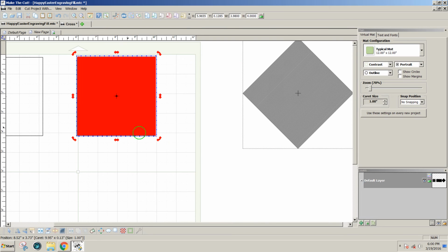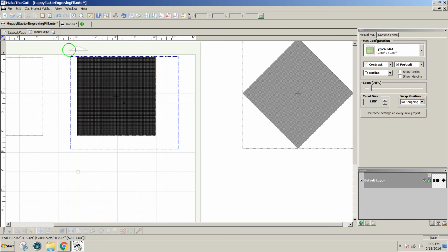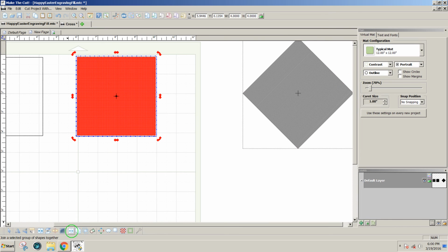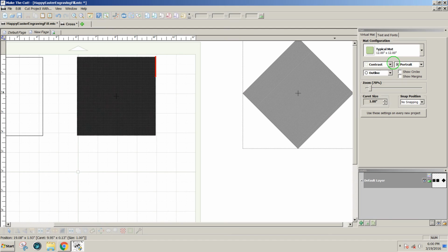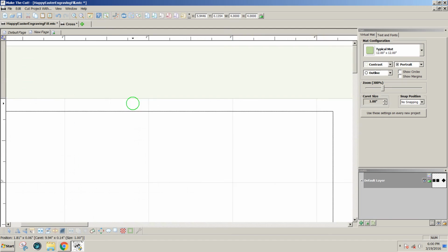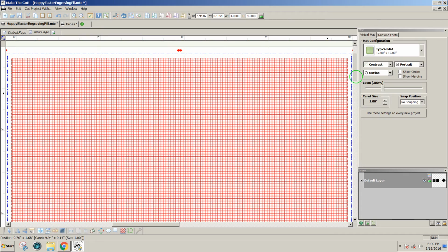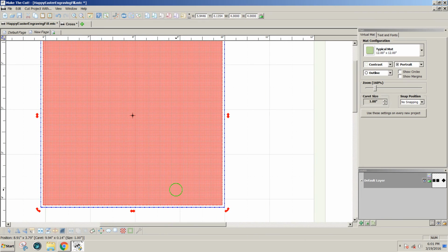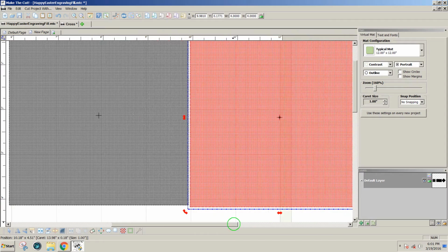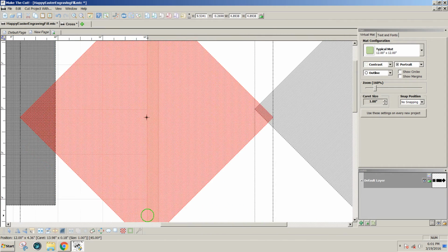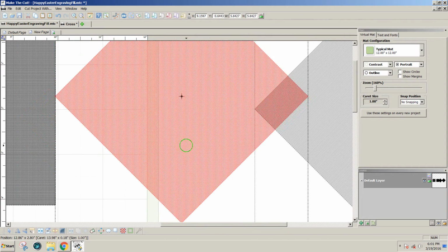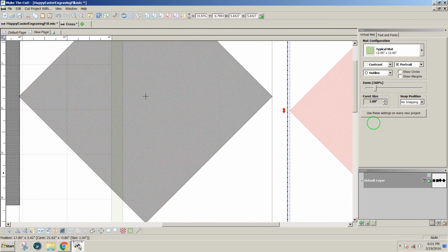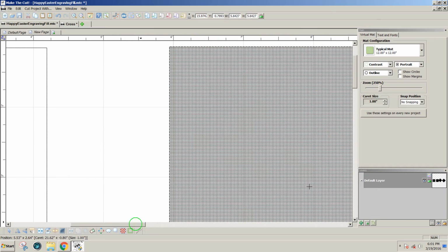Now if I would like to do a cross hatching, I can select both the horizontal and vertical and type S to stack, and if I join them, we'll zoom in on this and you can see that I have now little squares. It's cross hatching, but it looks more cross hatched if I rotate it. So I can take the same design, Control Shift and click and drag, and now hold my Control key to rotate, and now I've got something that'll look more like cross hatching in my design. So we can zoom out a little bit and see the difference.